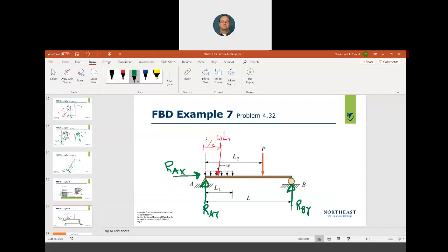Sum of the forces in the x, sum of the forces in the y, sum of the moments have to equal 0. All right? That's 3 equations. I can have a maximum of 3 unknowns to solve these equations. So that's why I only have 3 reactions here. This is why we have to assume one end is pin, one end is a roller, even though in reality, we know there's not a marble sitting on top of that wall there. That beam is actually nailed to the top of the wall. But we simulate it as a roller to make this solvable so we can figure out forces.